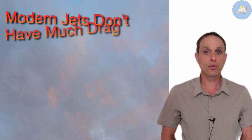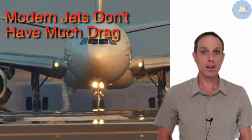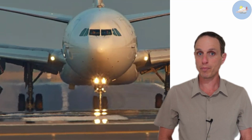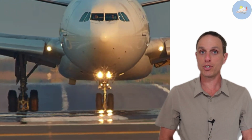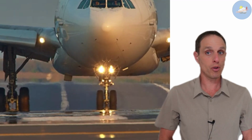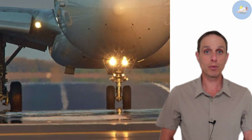Modern jets are incredibly efficient and don't have a lot of drag. If you waited too long to tell a pilot to descend, they might not have enough distance to slow down and hit that crossing restriction. Pilots will sometimes say unable to a clearance if they can't meet both the altitude and speed. They can either hold altitude to slow down or descend faster at a higher speed, but they can't always do both simultaneously.